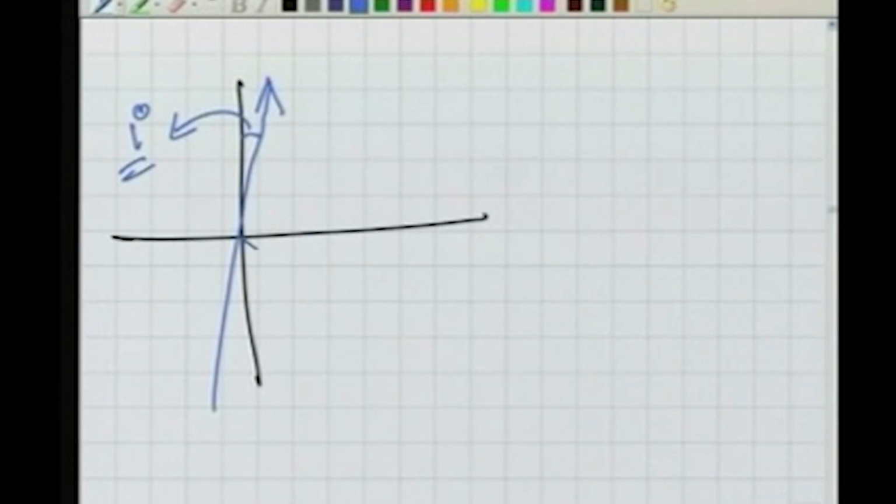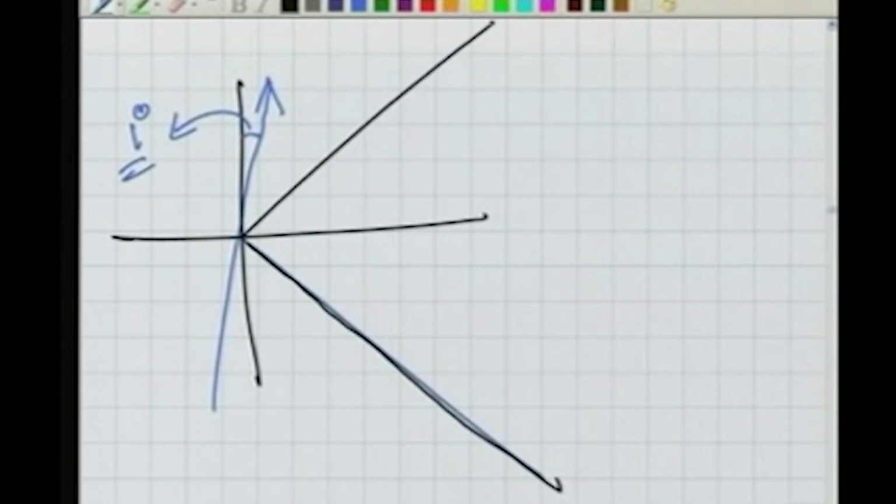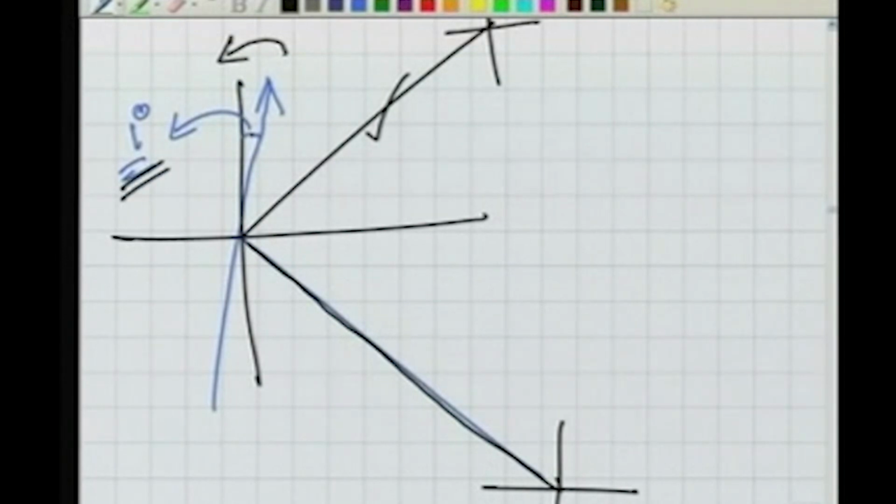Now there is another line. So the line here, these are the traverse lines. We applied the correction for this one, so this is also free of the local attraction here. Now we want to apply a correction for this. So what we know is that at this point the north was required to be rotated this way by 1 degree in order to apply the correction. This is what we have done.